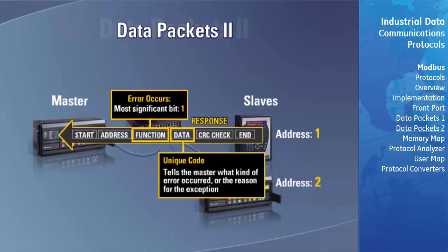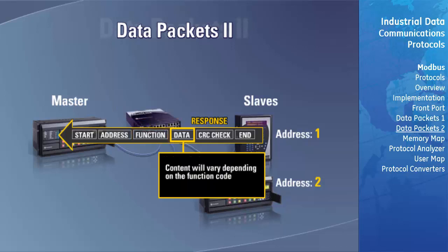The master's application program has the responsibility of handling exception responses. The content of the data field will vary both in the number of bytes and the content, depending on the function code. The content may be actual values, settings, or addresses.